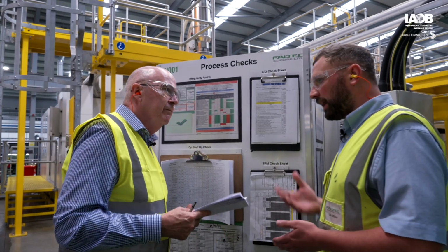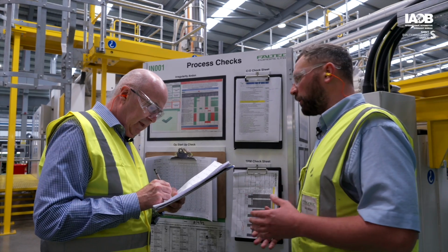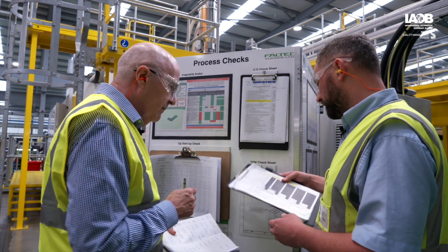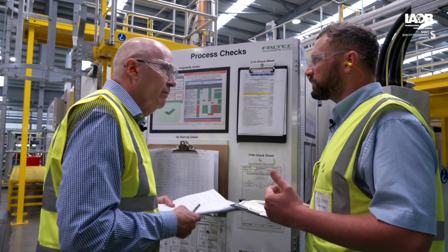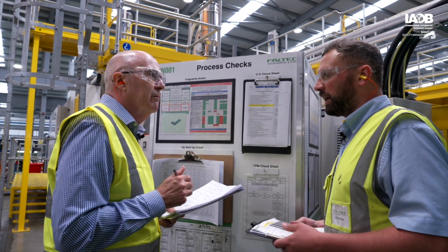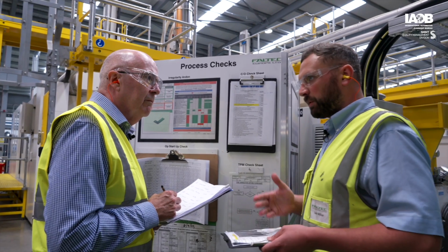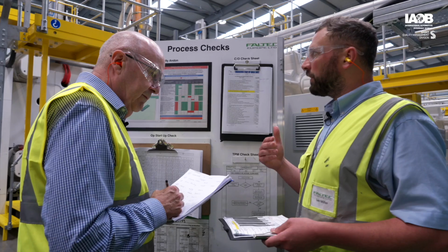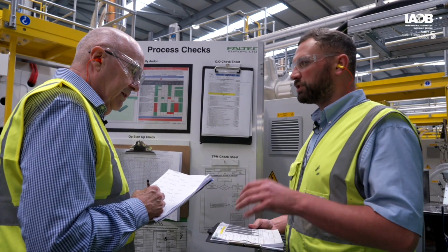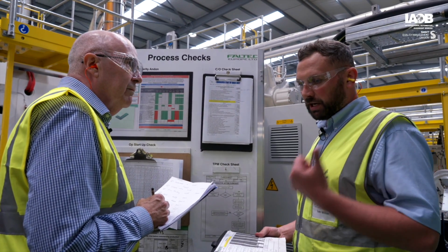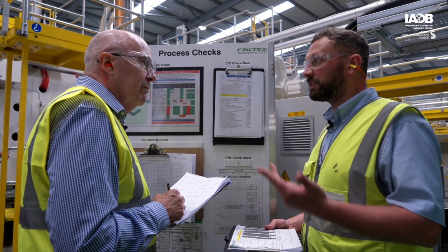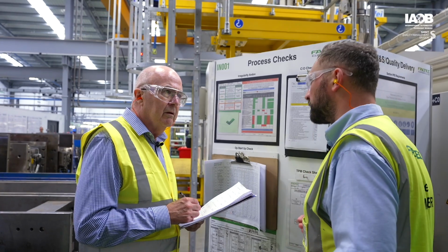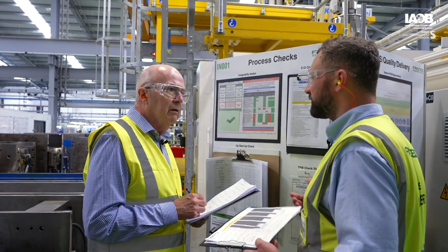So we have daily and we have weekly TPMs depending on what requirements are. They're all set on the schedule here, which is our TPM check sheet. Some of our TPMs are safety critical TPMs, so at the start of the week we do e-stop checks, certain stuff like that, that's covered in our TPMs. Our key functional TPM maintenance checks of the machines are checks of the oil levels, grease levels, lights working, to make sure the machines, when we start up, are operational, it keeps it going, and also awareness of when oil needs topping up, etc.